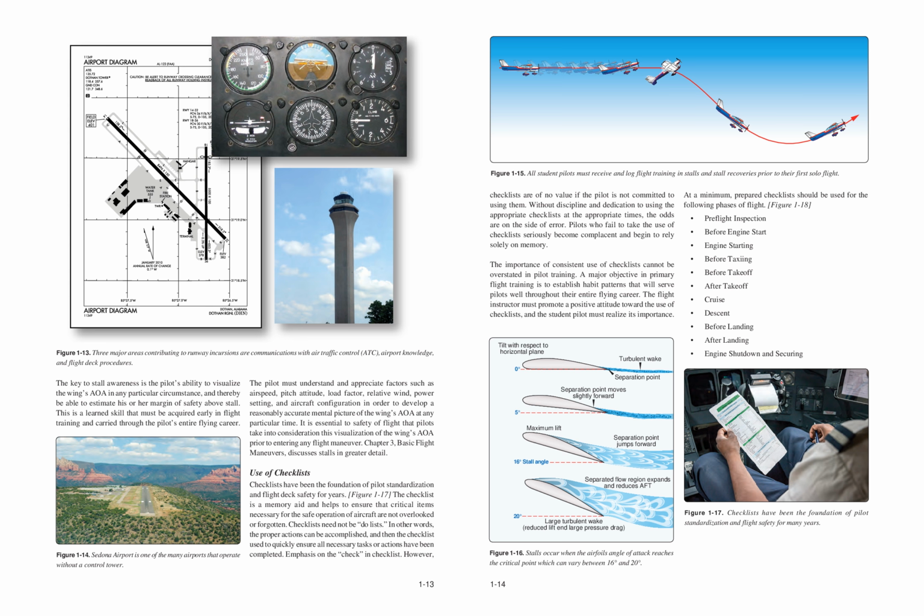Figure 115. All student pilots must receive and log flight training in stalls and stall recoveries prior to their first solo flight. At a minimum, prepared checklists should be used for the following phases of flight. Figure 118. Pre-flight inspection. Before engine start. Engine starting. Before taxiing. Before takeoff. After takeoff. Cruise. Descent. Before landing. After landing. Engine shutdown and securing.